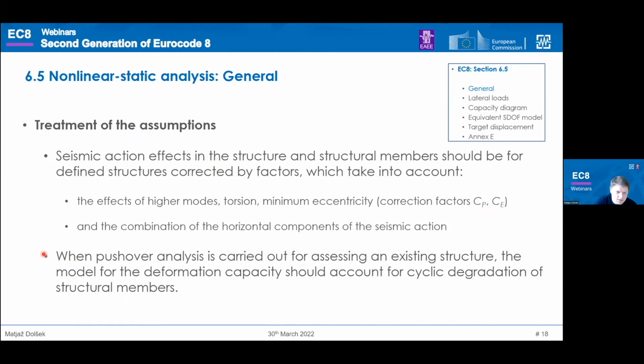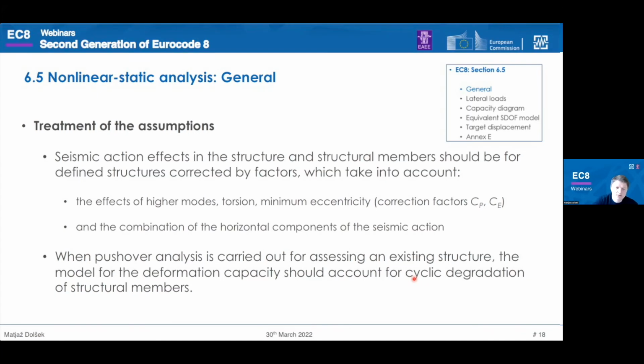And again, it is repeated that, especially for existing structures, the model for the deformation capacity should account for cyclic degradation. This is important because we use the pushover analysis, so we are not simulating any cycling. We have to account for this in the model for deformation capacity.